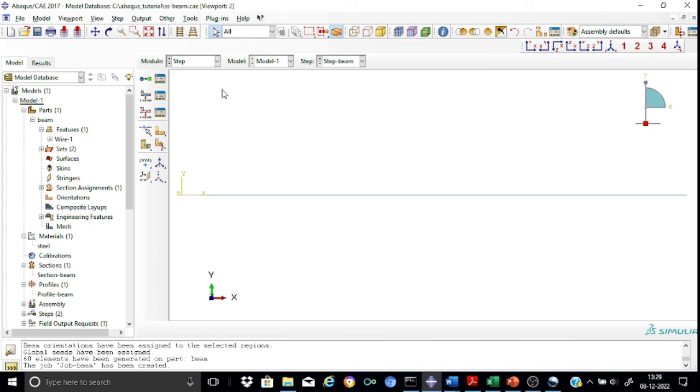For example, as far as the beam in the present tutorial is concerned, you would like to investigate how your shear force changes, how the bending moment changes, the variation of the deflections or the deformations, and how the reaction forces are changing. After an analysis, Abaqus writes thousands of variables, and many of them are not of interest to you. You want to inspect only some two or three variables.